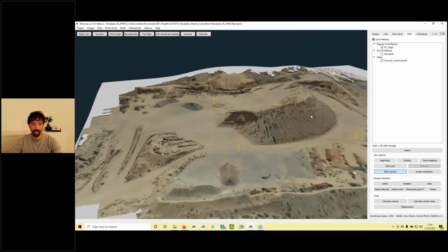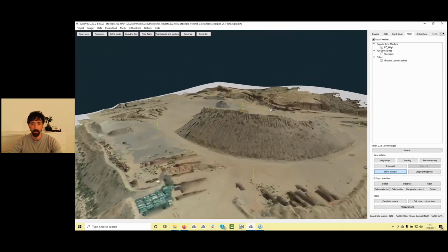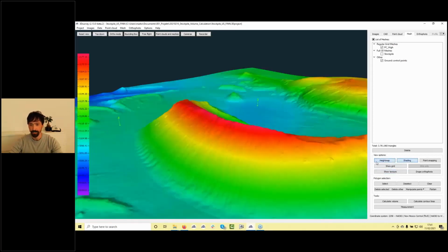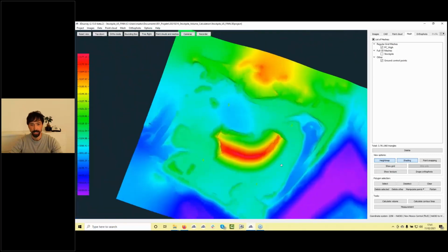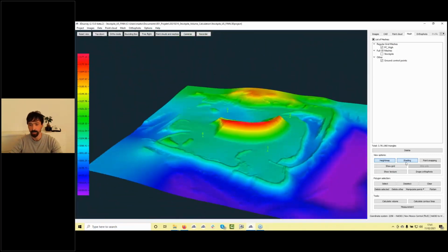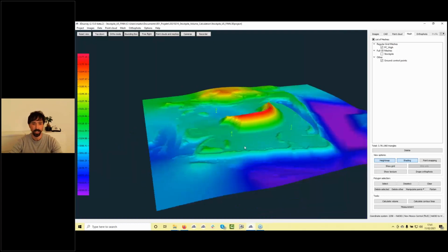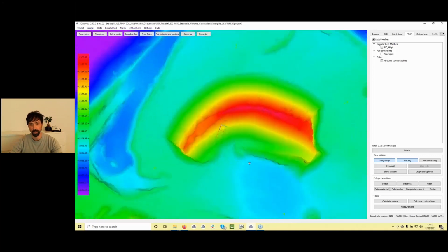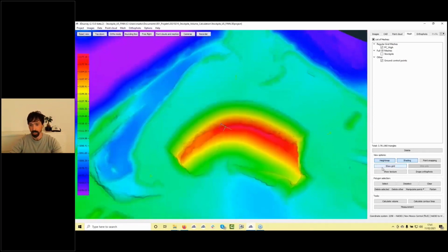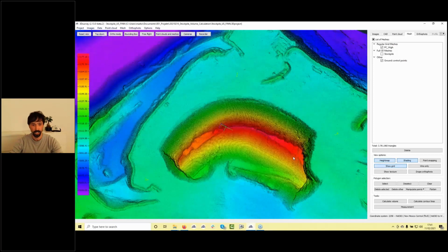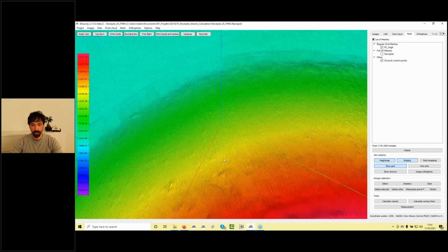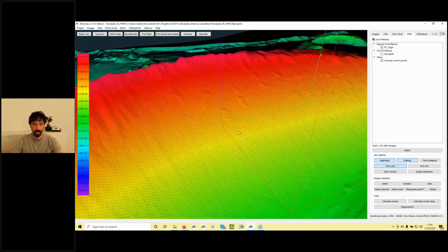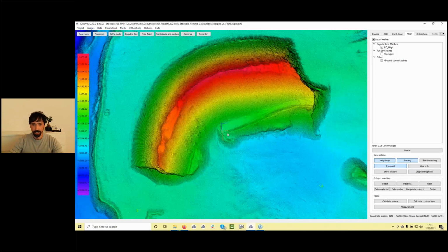And here we can see a nice smooth surface which is ready for volume calculations. Here we have different view styles available. So I turn on height map and shading, so you can see really nicely and in detail what kind of field you are working with. You also have the show grid option, just to show you. With the regular grid, we actually have a regular grid mesh with 1 feet. Okay? Perfect. Let's turn this one off.